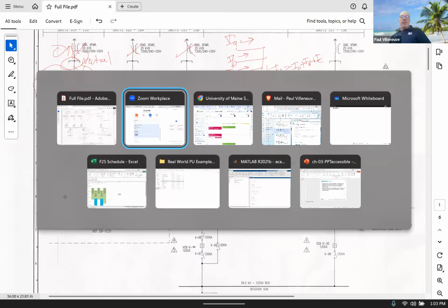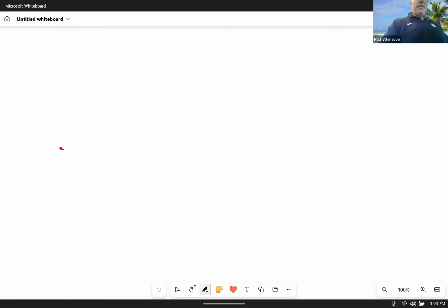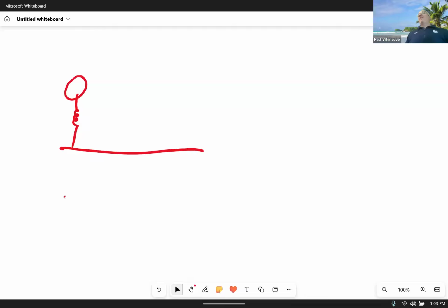So if I'm going to draw these on a per unit diagram, I have my bus, I have my generator, which has an internal impedance. Notice I didn't bother showing any cables or surge arresters or breakers. I have the generator voltage source, and that's it. Nothing else. There is no impedance connected to, we'll call it, the top side of the generator. So that generator we just drew is H5, and that is X generator H5. That's the internal impedance.